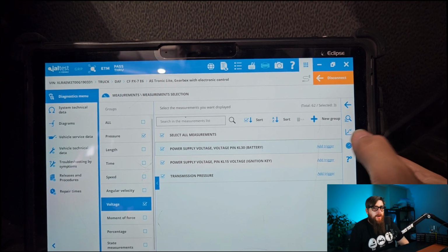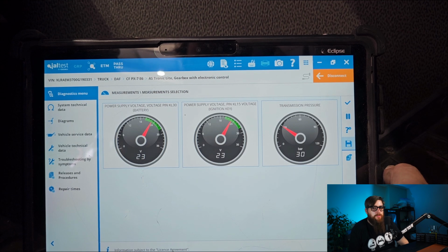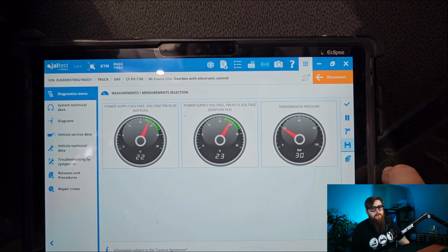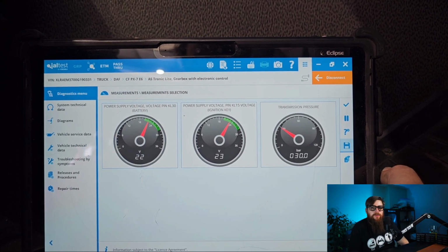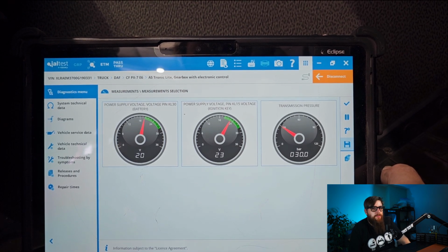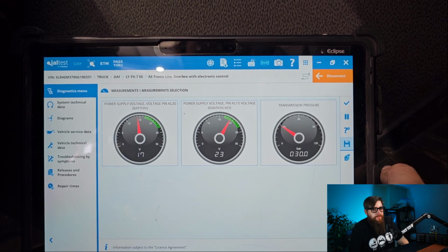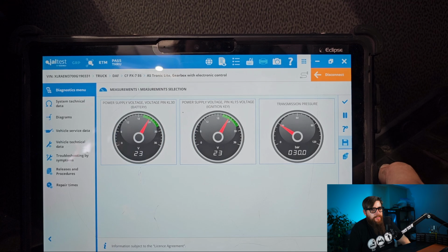By selecting the power and pressures here, it will allow me to identify when and what is possibly causing the issue. Well, we have no pressures for a start, and more worryingly, fluctuating voltage on KL30 at the pump. Things have just got a lot more interesting, so we need to get more invasive. Time to get the truck in the air.